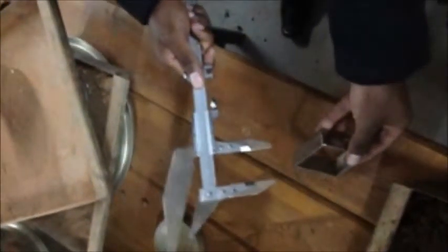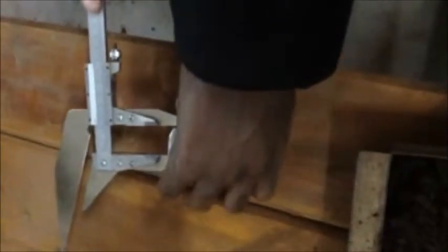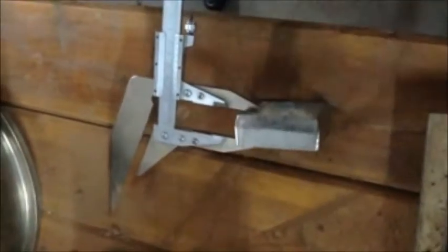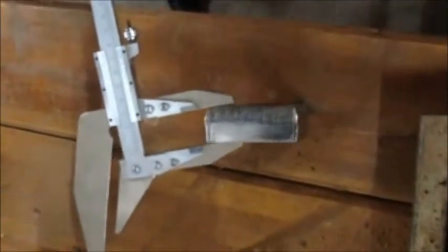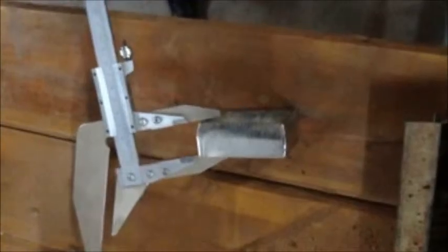I suppose that every material is at hand, so that we will not be disturbed by going away to find the materials. Remember, we are going to find two parameters, cohesion and friction angle. We first need to know the dimensions of the sampler. So we need to determine the height of the sampler and the width of the sampler.